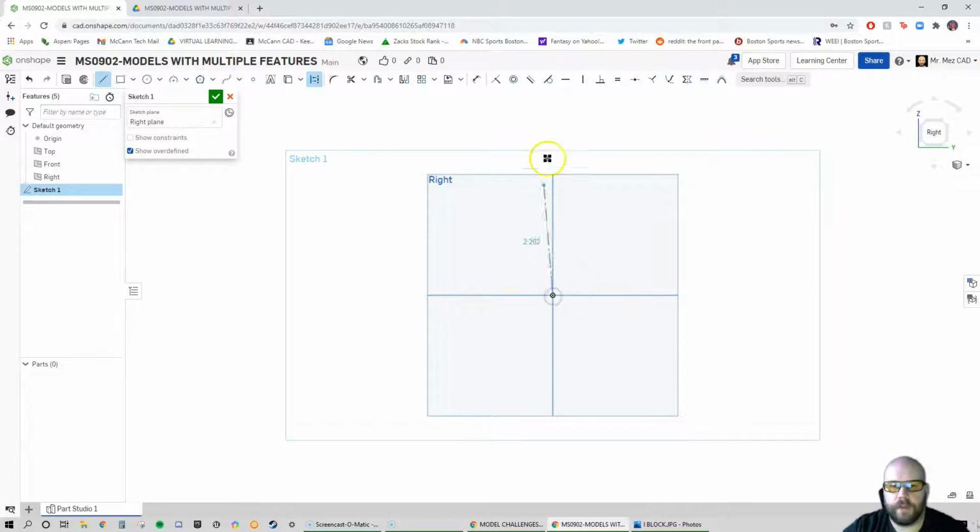And then let's put a vertical center line in. Let's hit escape. Let's hit Q again, or go up and click it. It's a lot quicker if you know the different shortcuts. And then let's click L again, and we'll draw a horizontal line here. Doesn't matter how long, just make it a pretty decent length. But you could also come up and click.